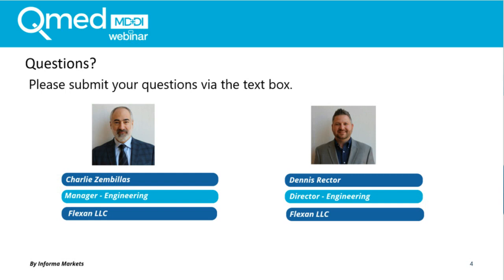Our next question asks, when overmolding silicone into a silicone tube, how much of an undercut is acceptable to still be able to remove the tool? Generally, as a rule of thumb for silicone, you can go 300 to 400% without permanent distortion of the silicone part. So when you're doing an insert molded silicone extrusion, you can use that as a general rule of thumb. Obviously, it's going to vary by the size of your product, but that's a good recommendation.